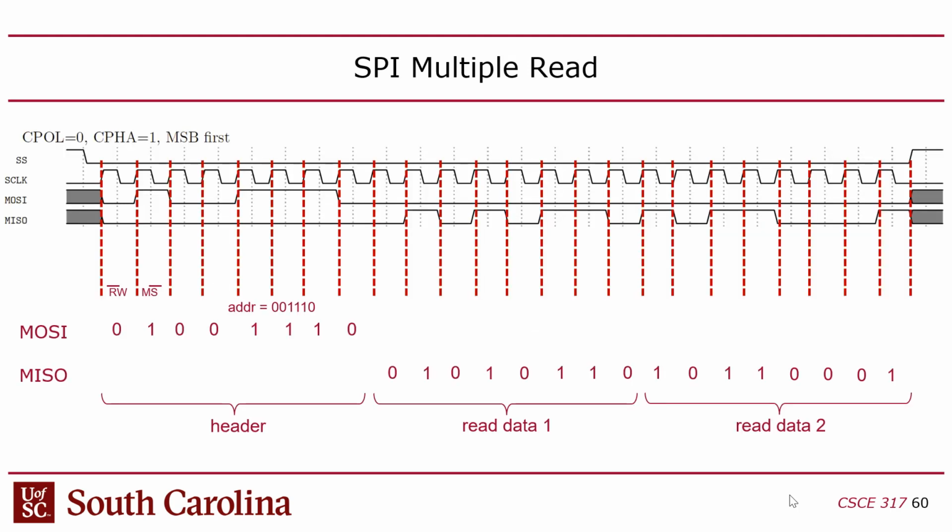So yeah, actually, this is a read because the first bit is 0, but the reason I know it was a read was because you see this data coming back to the requester on the MISO, the feedback line. So it must have been a read, which meant that the read bit indicator should have been a 0. So you put the bar above the R. Makes sense? Okay, and then the multiple is the logic high.